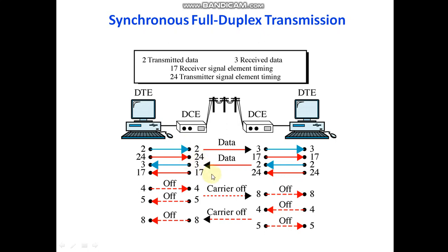The modem converts the digital signal to an analog signal and sends it out over the network. The responding modem retrieves the signal, converts it back into digital, and passes the data along to its computer via circuit 3. It receives the data through circuit 3, accompanied by the timing pulse at pin number 17.